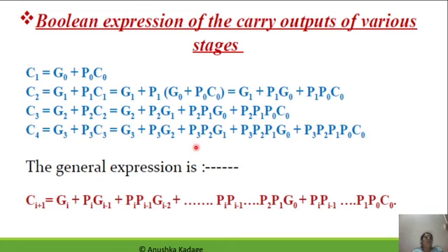So if the generalized form of the expression for the carry output to the next stage is to be written, then it will be given as follows. Everywhere, if I am adding the previous bits, the next bit carry is going to get generated. And that's why we will write the expression for C out as C(i+1). C(i+1) is nothing but Gi, that means the current input value which we are going to add with the subscript i.